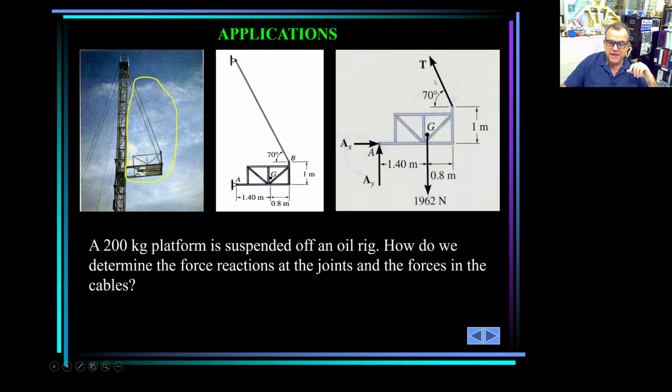As you can see, this is a cable, and I know, and you know, there is a cable that is coming in this direction. Why? Because cables don't push, period. You already studied cables before. Now at this point, this is a support that is called a pin, and you don't have to worry too much at this point about why I have these two forces here, but a pin is producing some internal forces here that are keeping the structure in equilibrium when you couple them with this cable. That's basically it. And then you have the distances.